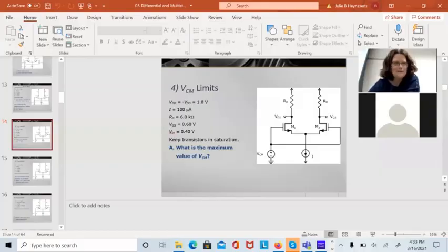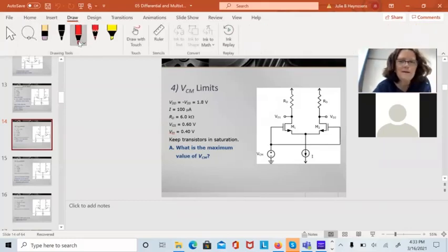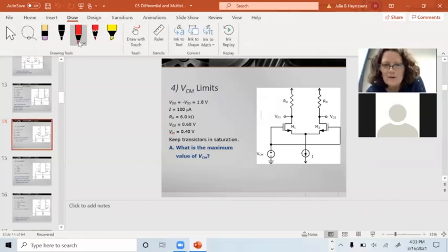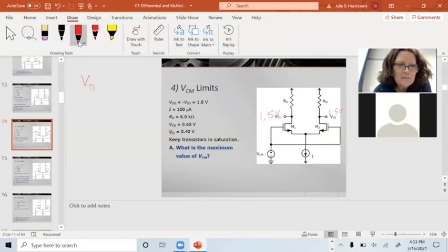And we are back. Okay, so what we figured out so far, in red pen, is that we know this voltage here, by the previous argument, is 1.5 volts, and it has to remain 1.5 volts as long as we only have V common mode on there. So we want to find the maximum value of V common mode to keep these in saturation. Well, to keep M1 in saturation, this sounds familiar. I need VD1 greater than or equal to VG1 minus VT.